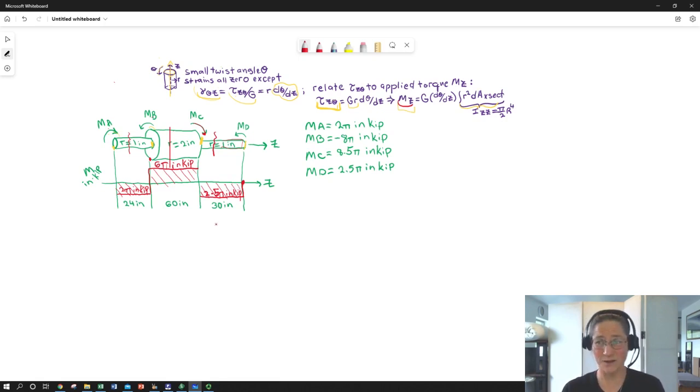So basically we can plop them into our equations, and then we can look and say, what stress would we need to have in order to achieve that? And what would be the resultant twist rate, or d theta dz, that would result from the combination of our shear modulus and our shear stress, and our shear strain, basically. We'll get that angle of twist through the strain. So at this point, we've got M.